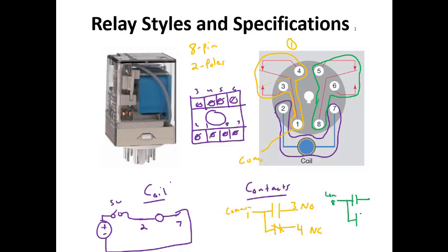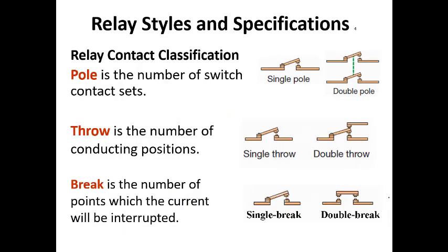And then the normally open, if we go here, we're coming up 8. This would be connected like this when this armature is going to move here. So 6 is normally open and 5 is normally closed.